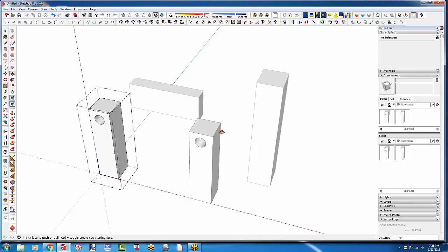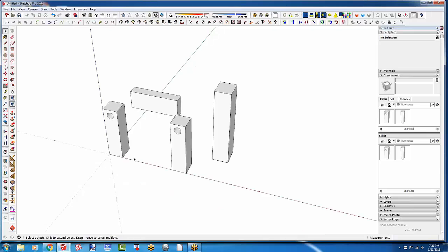And what I've found works best for me is to make every single part a component instead of using groups at all. I have never found a case where it actually made more sense to make a group than a component. And I can find all kinds of advantages for components that groups don't give you. So did that answer the question? Yes, it did. Thank you.